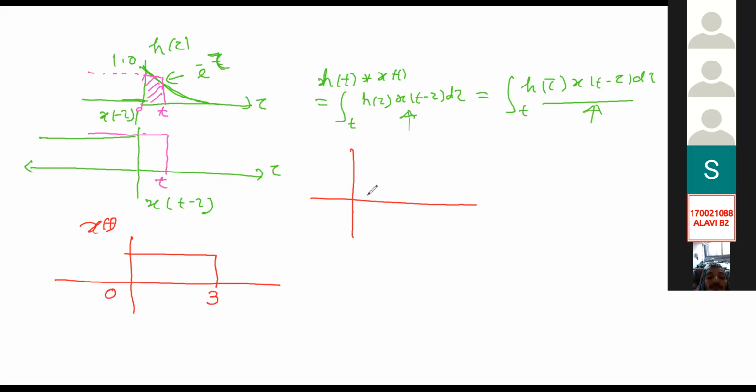If we plot it, say this point is 3. Consider this dotted line is the amplitude of your original signal. Then your capacitor output will begin to gradually charge and increase. Again, at this point, it begins to discharge, isn't it? Now your curve can go in this way, or in this way, or even in this way. It depends on the RC value. That value is called the time constant. You know about it.